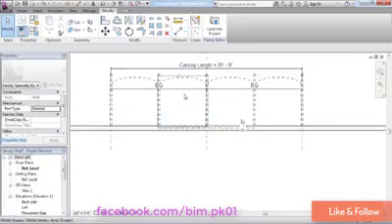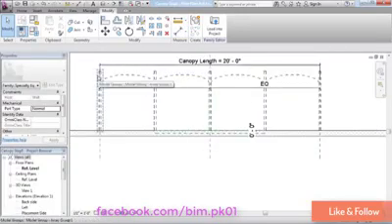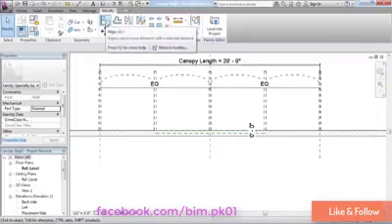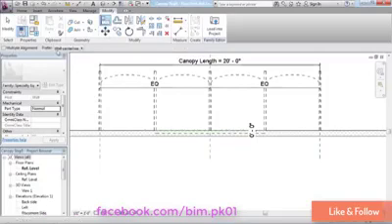This is actually a pretty easy thing to fix. When we brought in the original components, we just placed them relative to the wall, but we didn't actually lock them to the face of the wall. We just got them nearby. What I want to do is use my Align tool here, and I'm going to change the preference to wall faces, pick up the face of the wall, and then the edge of the bracket, and I'll lock that.